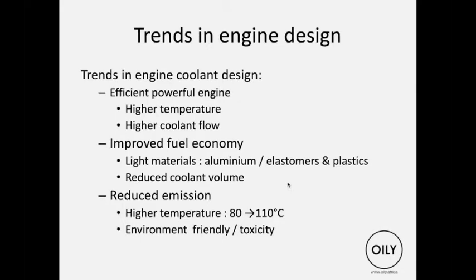But in engines, there is a move to smaller, higher efficiency engines. So there's less coolant flow in the engine, and the coolant has to do more work. Because of that, the operating temperature is getting higher in engines. It can be over 100 degrees, and to prevent the water from boiling in the cooling system, the system is pressurized. There's also a move to lighter materials, a lot of aluminium used in engines, and even plastic parts.